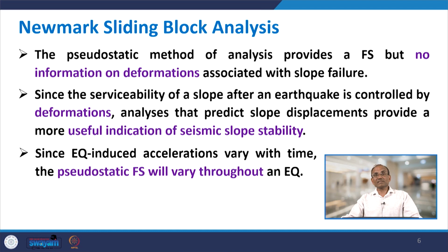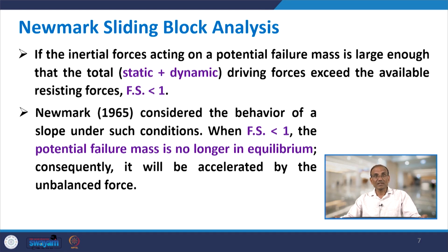Since earthquake induced acceleration varies with time, the pseudostatic factor of safety will also vary throughout an earthquake. The good point with numeric sliding block analysis is that a rigorous analysis may require finite element methods and software, whereas numeric sliding block analysis can be carried out analytically. For the simplest case, it can be done even using a hand calculator or an Excel sheet. We will come to this, and it gives you the factor of safety as well as information on the deformations.